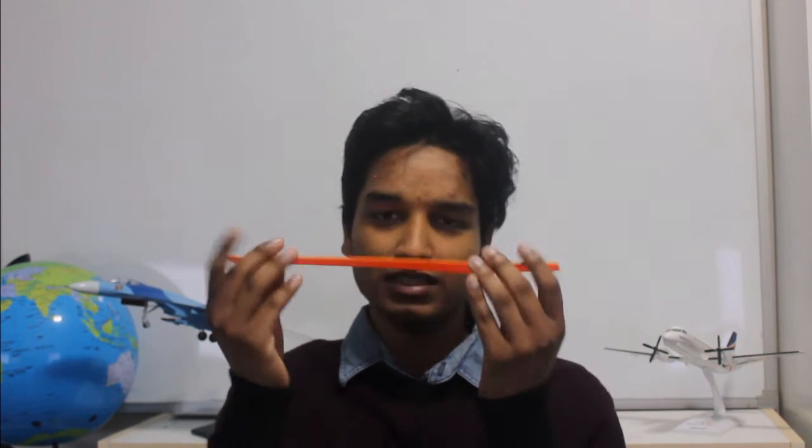For this analysis, I've assumed the wings to be a fixed cantilever beam, similar to this ruler here. So, one of the sides will be fixed, the other will be free to deflect around. This will be critical in finding the resonant frequencies. The meshing and the results, including the nodal analysis and the harmonic analysis, will be discussed in the answers section.